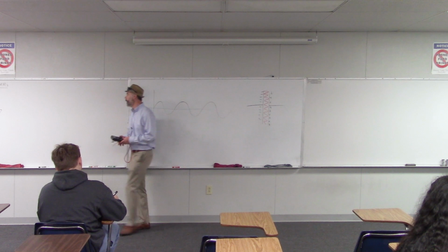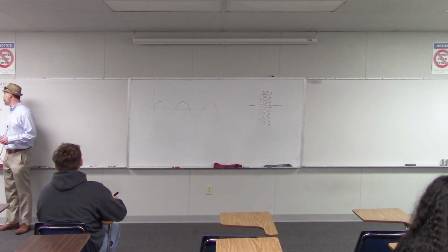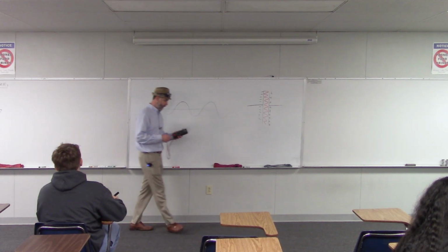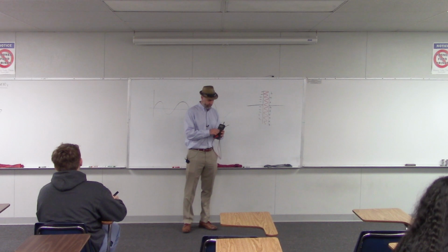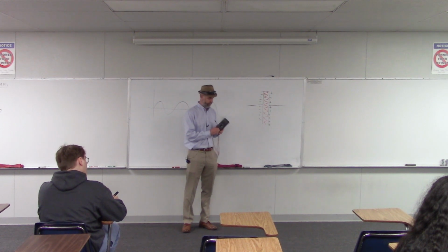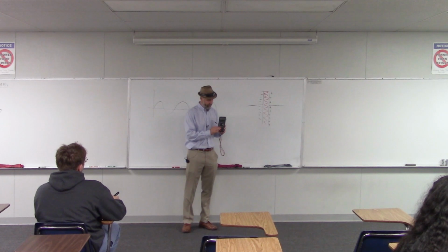All right, cool. So then finally, we talked about measuring high current. So we said that this DMM could measure low current or high current. In order to measure low current, you would put the black lead in the common port and then the red lead into this milliamp port here.